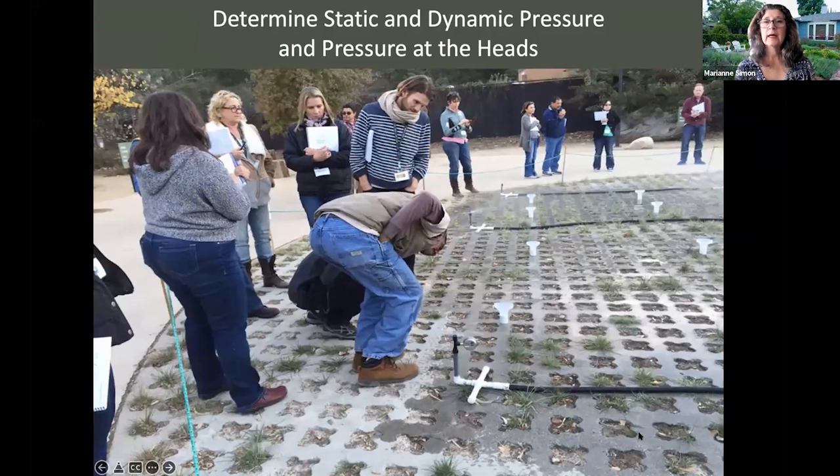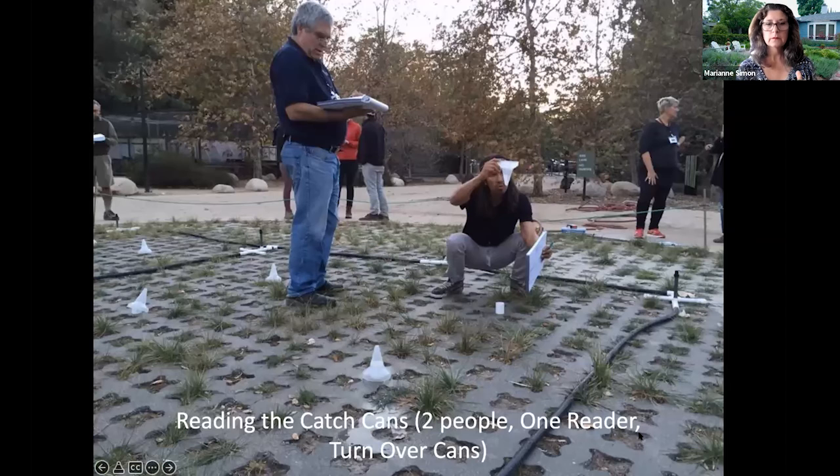Things to check. As the system is running, or actually before, you want to check your pressure, key thing. You're checking your static pressure, which is when the system is not running, and the dynamic pressure when the system is running. And then you also check the pressure at the heads once the system is turned on for the audit. You want to check it at the beginning head, and then you check it at the end to see what sort of loss you are getting in your distribution.